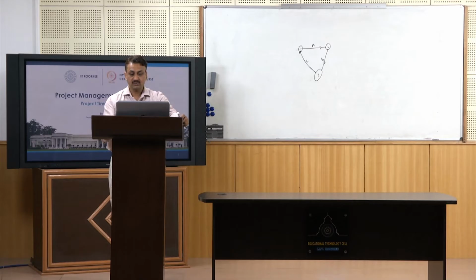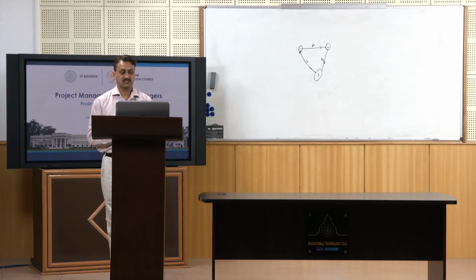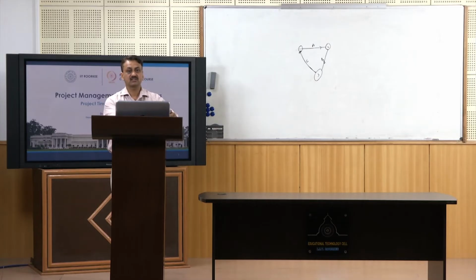So, what is the loop? The loop is 2, 4 and 5. How did we come to know this? Because there is a unity value, or value 1, across the diagonal cells. So, this is how you can identify whether a network is consistent or inconsistent. If there is a loop, it would be called inconsistent, otherwise consistent. So, this is a better method to identify closed loops in large networks.